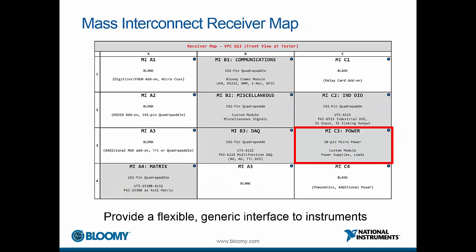The pinouts of all modules must be defined before continuing on with your design, but when you are finished you will have a detailed map of the entire capabilities of your ATE. This will be used as you transition to the next step, which is designing your ITA, or fixture.